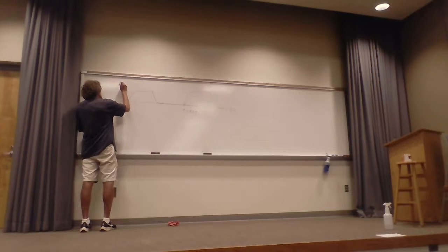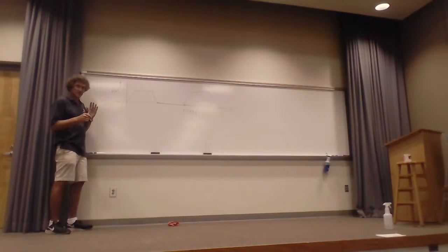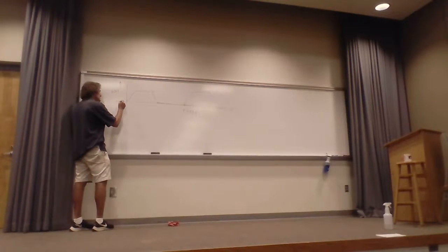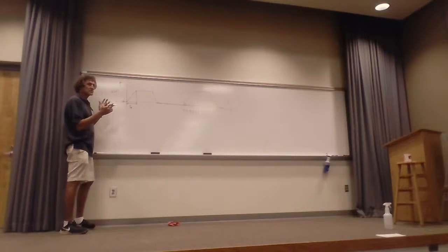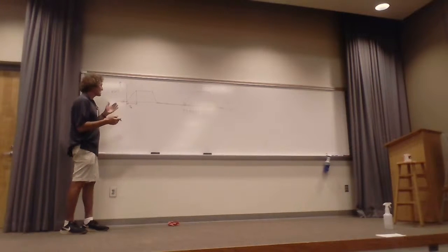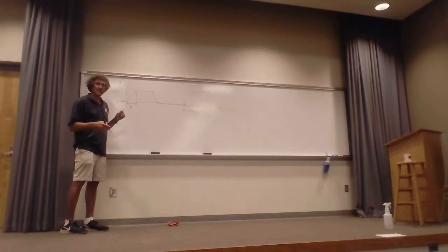This is going to be a digital signal. We might as well call this V of t because we're electrical and computer engineers. So it's voltage versus time. This is 0. Now, this is usually termed the rise time. I know we'll get into arguments about that. If you were talking to Dr. New, he would say it's the time that it goes from 10% of its maximum value to 90%.